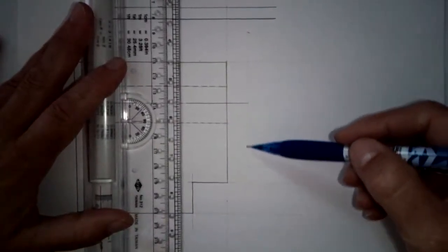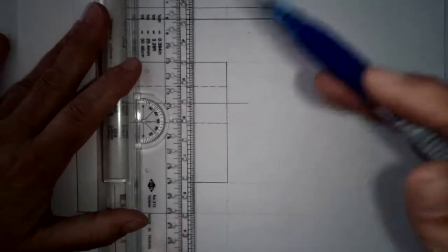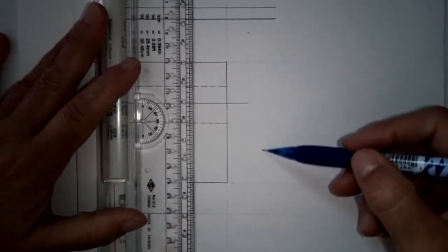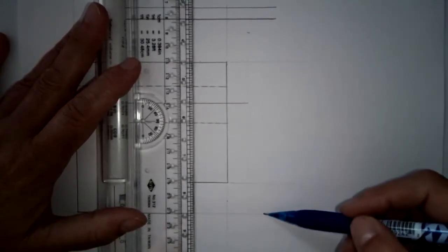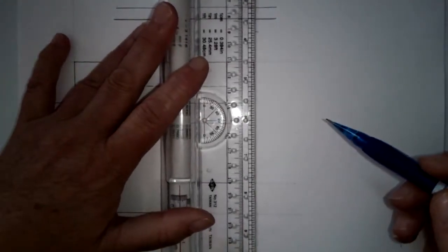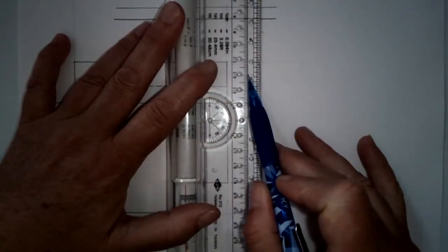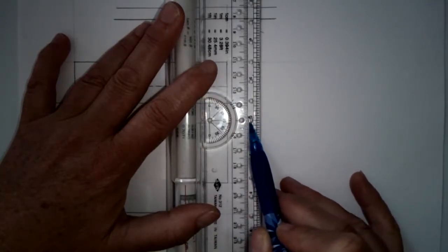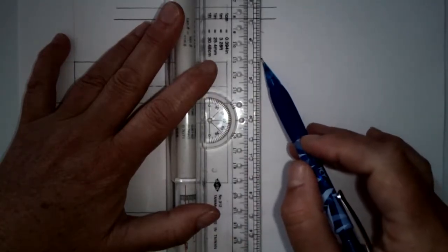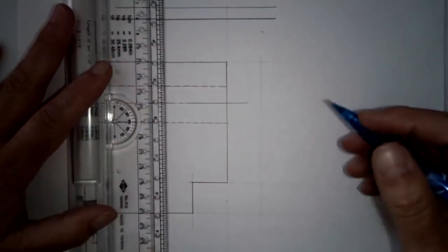And I'm only going to draw that construction line to the first of these two extension lines, because then the next dimension line is going to continue and be a baseline dimension from here to this point right here. And in this case, because I'm putting a second dimension line in, the distance from this line here to the edge of the straight edge is about 1/4 inch, and that's what I'll use to locate that second dimension line.